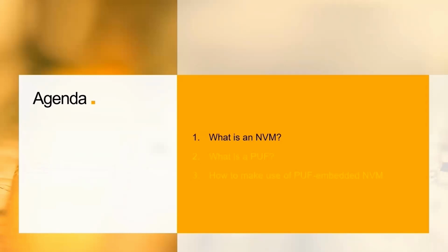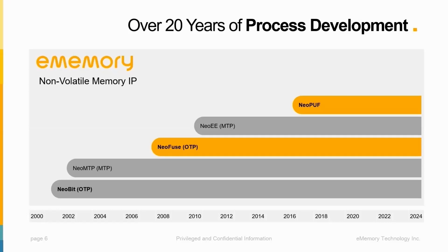What is an NVM, or non-volatile memory? By definition, a non-volatile memory is a device that can store information even after its power is removed. People typically think of hard drives, floppy disks, or CDs on a computer, but we would like to dive a bit deeper than that. At integrated circuit or IC level, where tiny circuit devices called MOSFETs, along with much smaller capacitors or resistors that make up an IC chip, there is also the need for a hardware-level non-volatile memory solution.